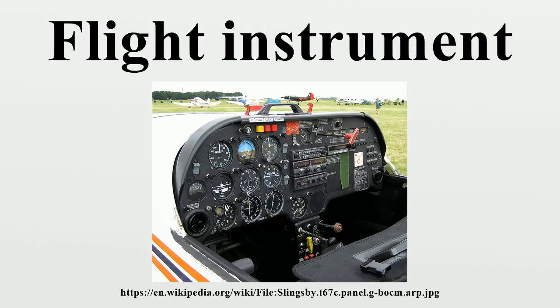The instrument was included, but it was of little use in the first generation of jet airliners. It was removed from many aircraft prior to glass cockpits becoming available, with an improved artificial horizon, including gyros and flight directors. The turn and bank indicator became needless except when performing certain types of aerobatics.